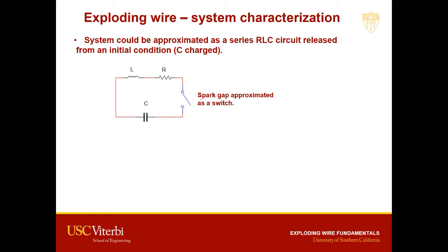The most common way to activate this electrical circuit after the capacitor has been charged is by means of a spark gap, which is basically a device that looks like a capacitor, and you trigger it using a high voltage. You fire a spark onto one of the terminals, and this begins the ionization of the air inside of the spark gap, or whichever gas you have inside, and then this triggers a large avalanche effect, and you have a large spark going through these main conductors. So the spark gap is a very fast switch, and it has its own advantages in relation to mechanical switches.